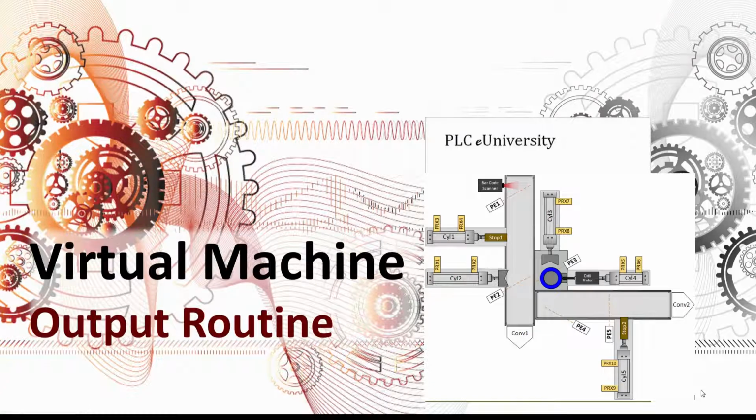More discussion of our virtual machine. Now we're going to do an output routine. Typically, most programmers create a separate subroutine with all of the output logic in it, meaning rungs where the result is turning on and off an output bit, and then they put all the logic specifically for that output, just turning it on and off in either manual or auto mode, into that rung. And then from the other routine, the main routine or the sequence routine, comes the actual result, the logic that actually tells that bit to either go on or off.